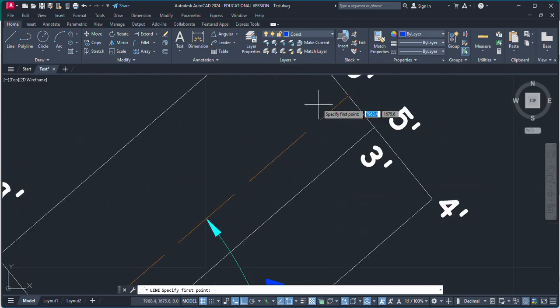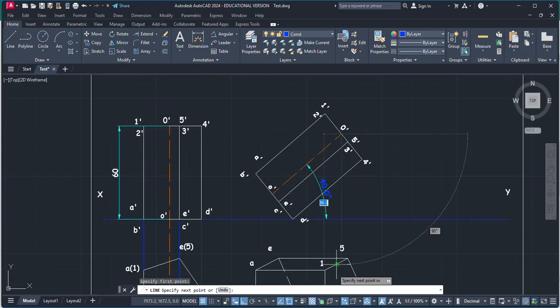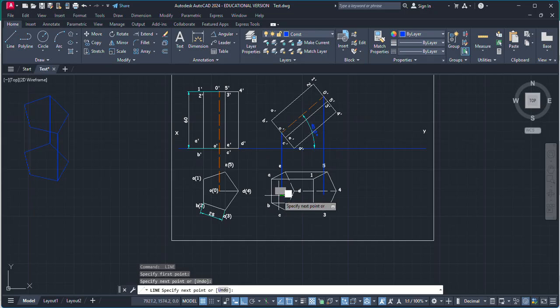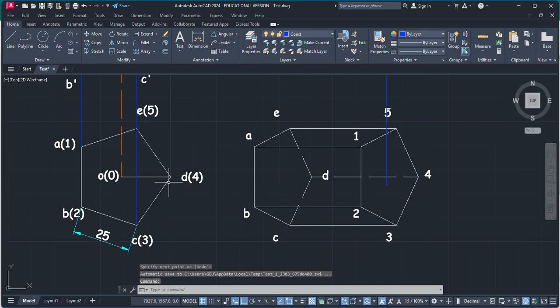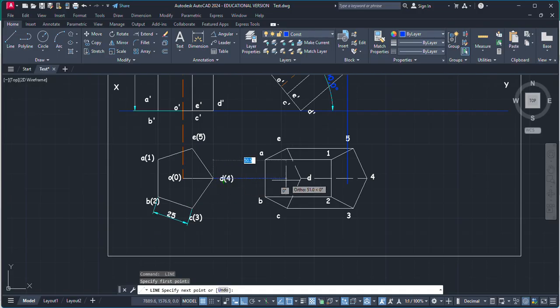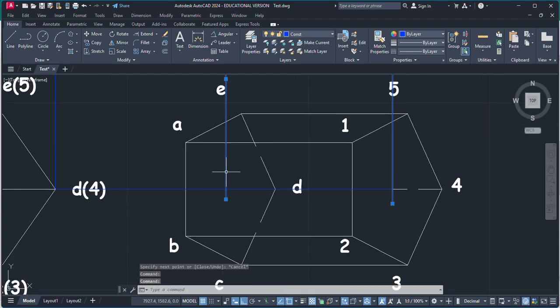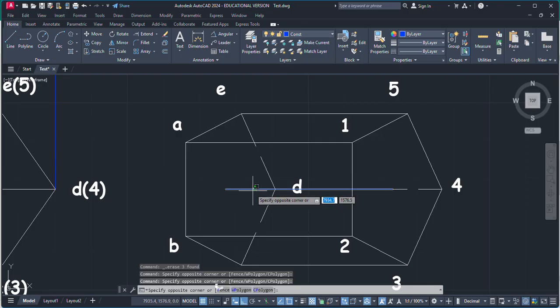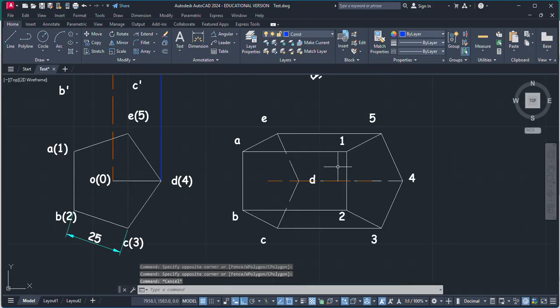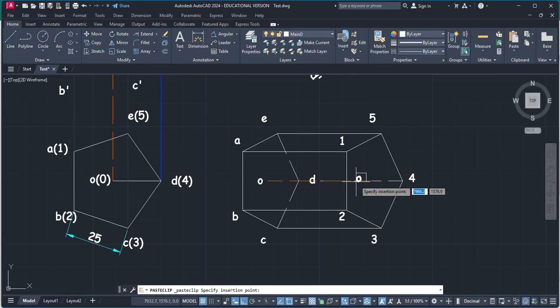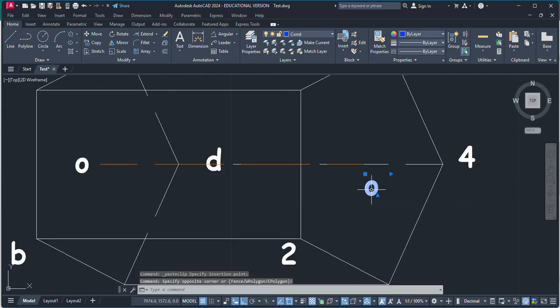Now we need the central axis. So just from this O dash, draw a vertical line, and from this O draw a vertical line. Now this is our center line on which we have O dash and O. So draw a horizontal line which will intersect first, then with this here. Now remove these lines. So this is our central axis. Change it to the axis, and this left one is O, and the second one here on the right. This center is